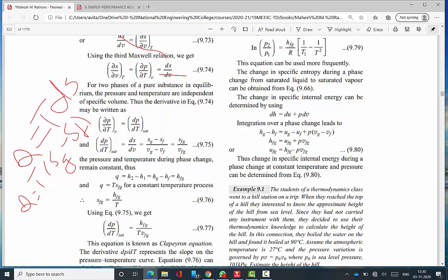Okay, it's a main concept. Partial dP by dT at constant volume can be rewritten as dP by dT only during the phase change duration. In remaining durations, partial and direct derivatives are not the same. So only for phase change time can I put the Sg and Sf. Sg is gas, Sf is liquid. Therefore the fluid is continuously converted from liquid to gas. I said only the phase change duration.